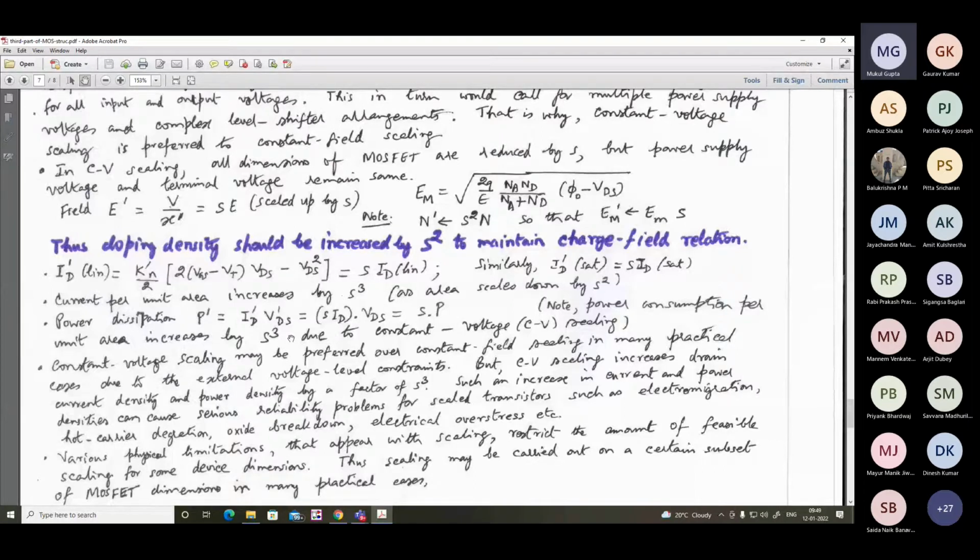But we have to progress over technology. We have to progress over the need of the day. So some mechanisms have been brought in to control this, but we cannot totally eliminate it. That means hot carrier degradation, oxide breakdown, electromigration, all will be present. So we have to limit the current to some extent, taking care that the current does not go past a particular limit. Also, we have to keep watch on the value of the maximum field that the designed circuit is subjected to. Keeping all this in purview, we need to take action.